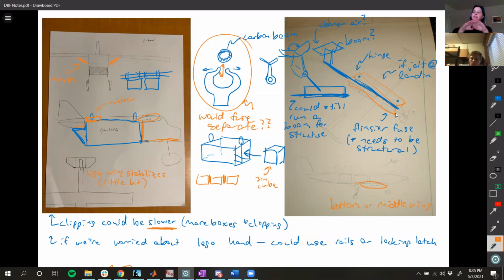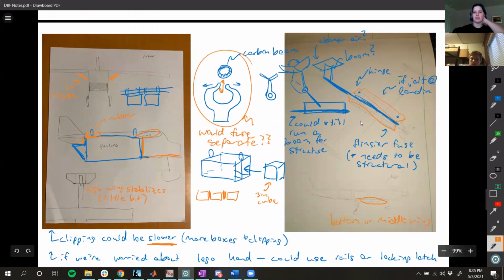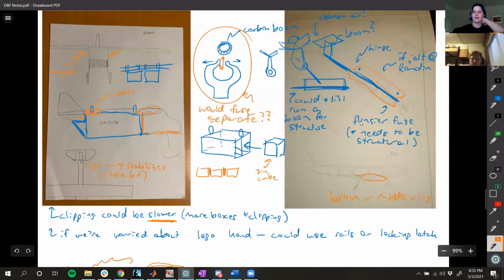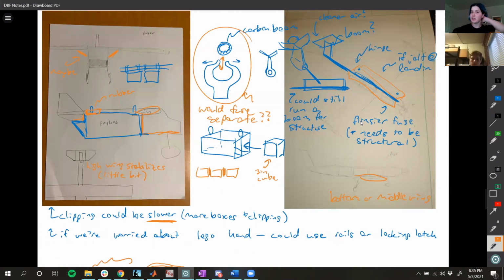Like I was saying, sometimes you'll have a foam wing and then you'll just put caps on top. Also when we talk about a leading edge D-box, you can also do a foam leading edge. But then you wouldn't get the torsional structural rigidity. But we're not really familiar with the load, so we don't know if that's a big deal or not, but it's another option.